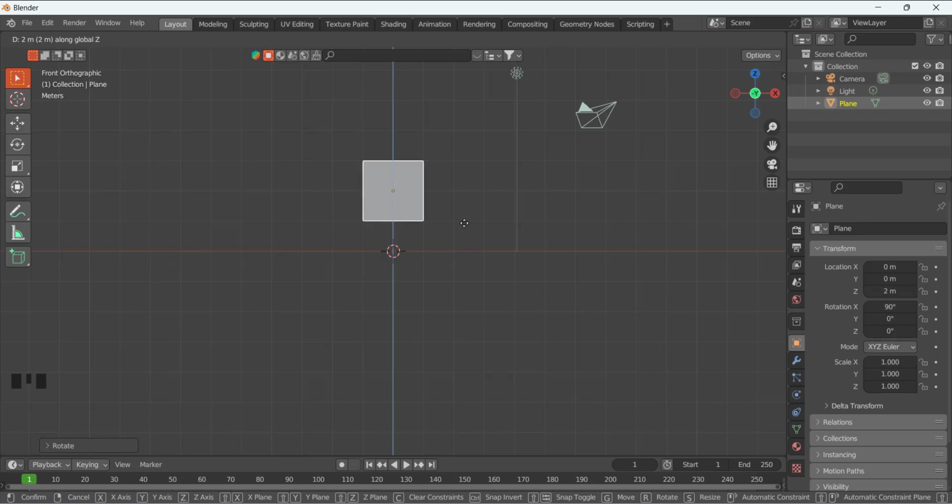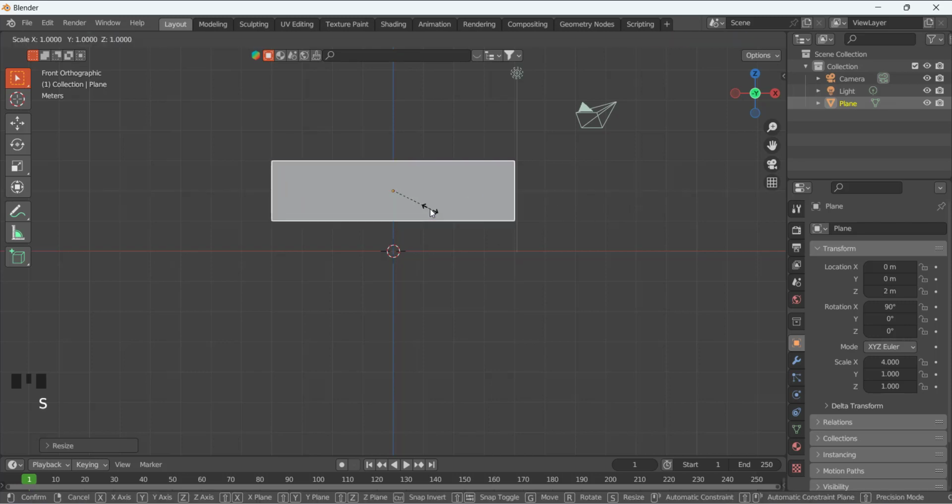Press the control so you can track it as to scale. And now I'm going to scale it along the x-axis like that. And if I press the control, I can see it's snapping with the grids like that, or even like that. That's good. And then S and Z, and again I'm going to press the control.